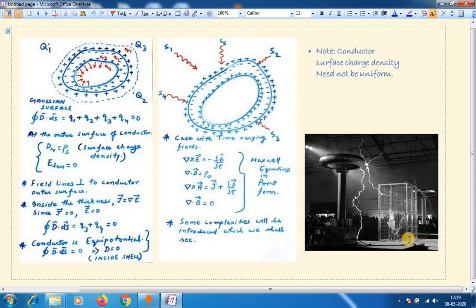Say I ground this point and I ground this point also, 2 grounding points, and this lightning jolt strikes here. So what will happen? This current will distribute in smaller elements because it is a cage like structure, and each distributed current will give a very small potential drop between any 2 points, isn't it?